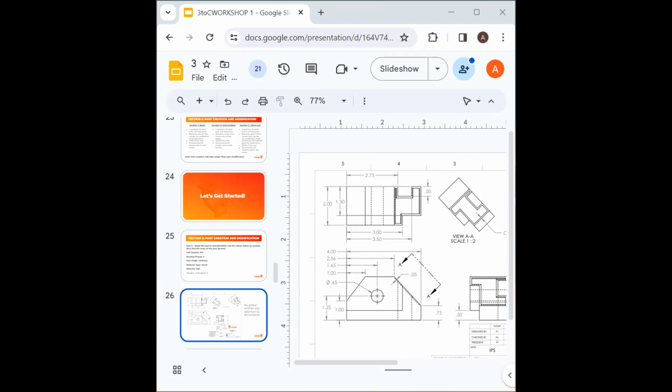You may notice, first of all, that it's just boxes. And if you want to keep it as simple as possible, you should use this specific square, which is the corner rectangle, because then you just click on one point and then click on the other, and it'll create that rectangle without you having to do 4 separate sides. Click on it. And then you dimension it the same way that we did the thought process of the first part. So I know from this side to this side of my drawing, it was 2.75.